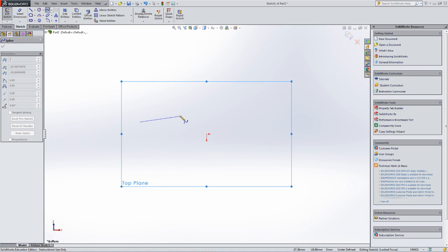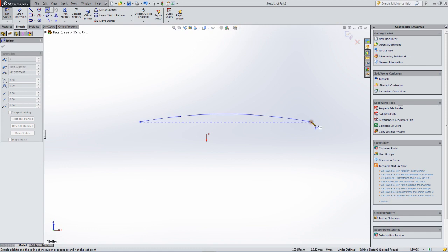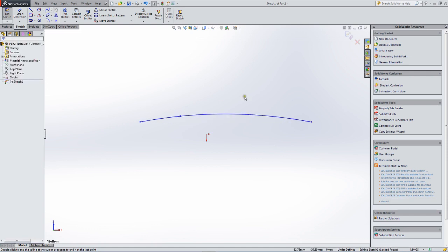The spline is, real splines in mechanical drawing, are flexible steel rods, very slender rods that can be bent to go between points on a drawing board. And so what we're doing is defining points, and the math of a spline is used to define the lines here that define our airfoil. This is going to be a fairly thin airfoil. I'm making it go out pretty far. It's got a little bit of camber. That's my upper surface. I'll hit escape. Hitting escape exits the drawing of that spline, and now to draw the lower surface I go back and select spline again.